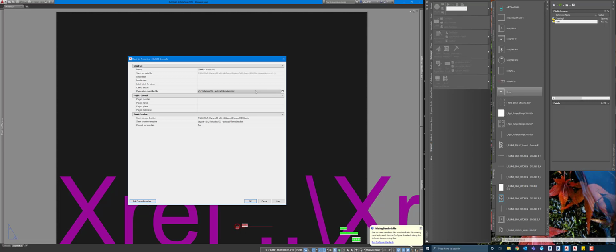This is fairly important. Your office that you work at will almost always have a template file or a .dwt file. And these .dwt files are exactly the same in every way as a DWG file. It's just a slightly different format that's set up so that when you click on it, AutoCAD creates a DWG. Think of it sort of as programming in the background. Your template files want to be .dwt files. That's just the way AutoCAD or AutoCAD Architecture works. You can take any AutoCAD drawing and turn it into a DWT file by right-clicking in AutoCAD, saying Save As, and doing Save As .dwt file.